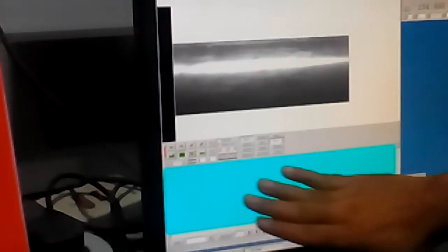Always remember that in the program we have 3 steps: start of the program, body, and end of the program. Those 3 things you enter here. Once they are ready, you can go for Auto and press Cycle Start so that it will do the simulation. For example, I can load one program here and show you how it looks. I'll load the sample program here.